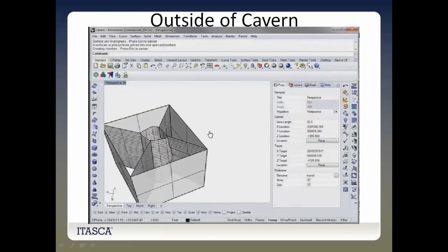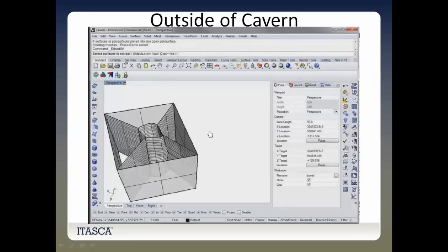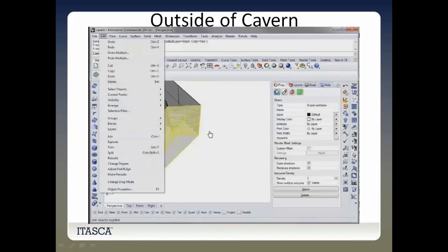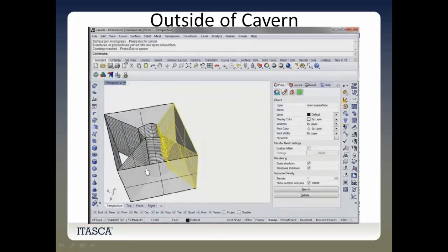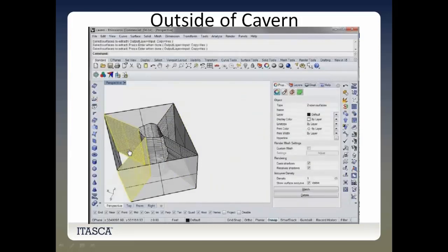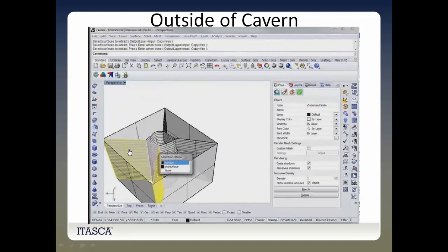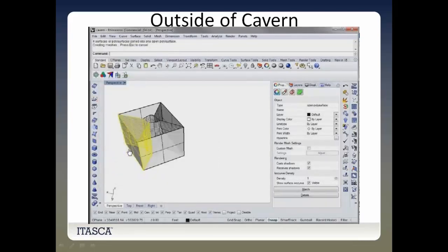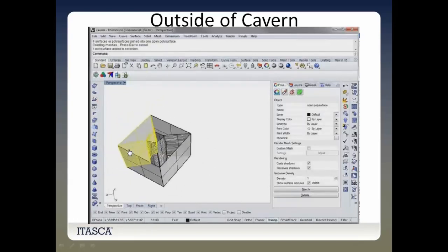What I'm doing here is creating these various blocks. I'm assembling the various surfaces, and this is kind of a detailed live tutorial. And the net result is a FLAC3D mesh that you can directly read into FLAC3D. Now that I've created basically 1, 2, 3, 4 poly surfaces, I now go ahead and cap these things into 4 solids, and I'm then able to create my 5 solids, including the inside of this model, to cap.